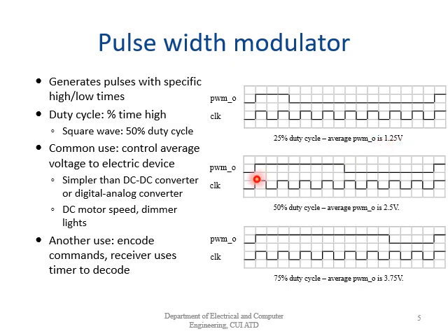Similarly, you can see here that half of the time our signal is high and half of the time it's low. It means that our duty cycle is 50, and we have a maximum voltage of 5. So 0.5 into 5 is going to be 2.5. It means that our average pulse width modulation voltage is going to be 2.5.